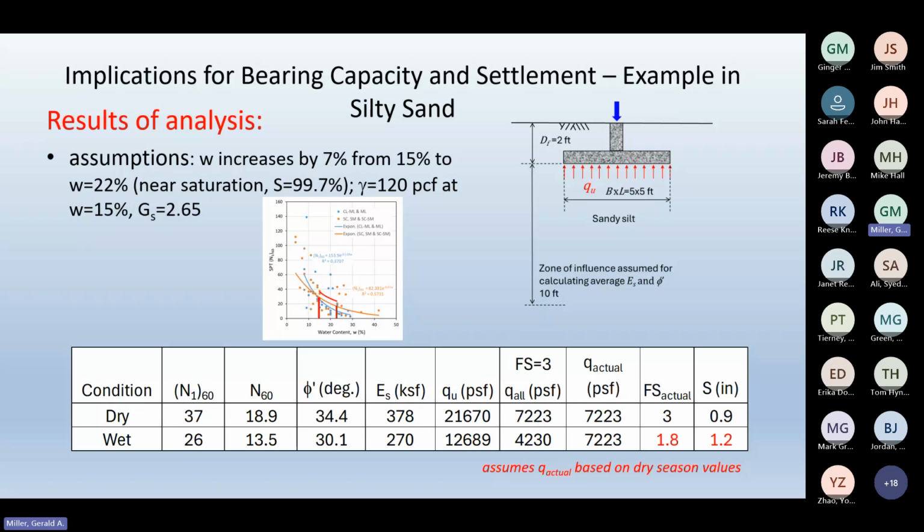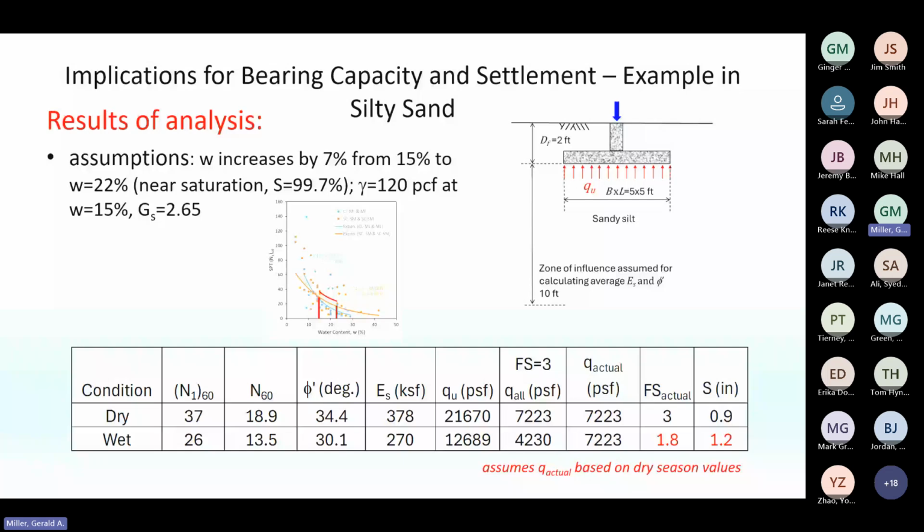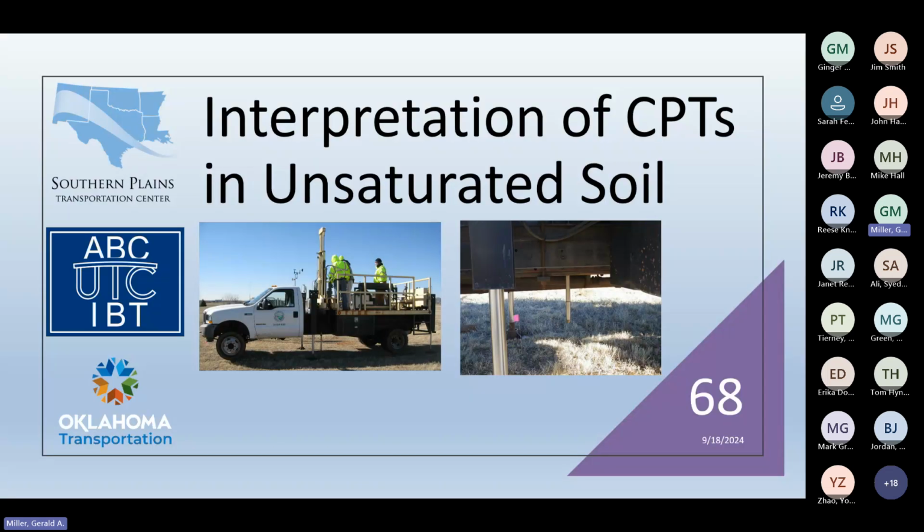Any questions? All right. So next, we're going to spend a little time looking at CPT results. I know more and more of you are using cone penetration tests. I think it's an awesome test for a lot of reasons. But again, in that unsaturated profile, those results are going to be impacted by the water content and the state of suction. And so we'll look at that next.